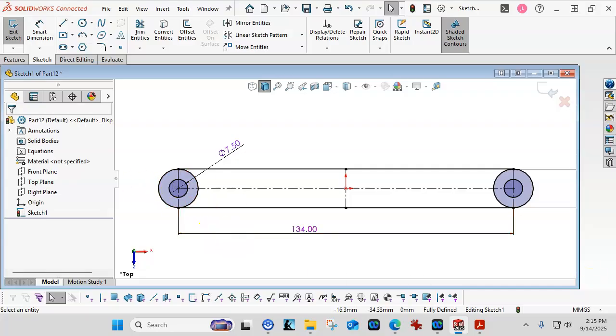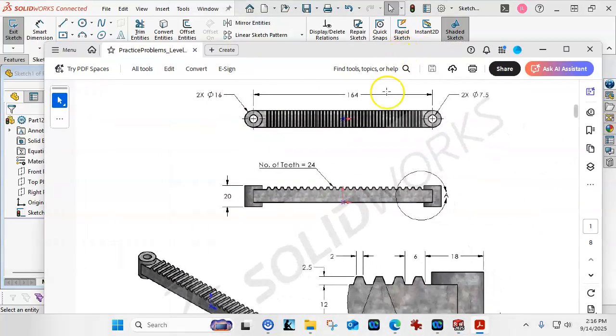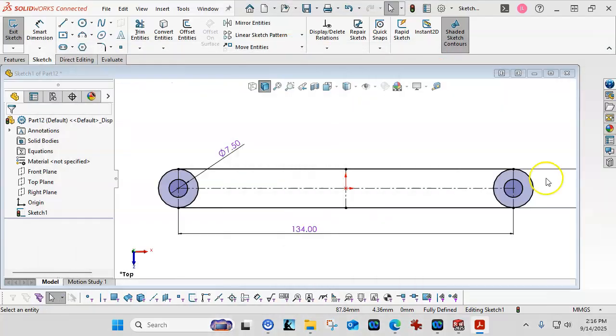Since we're going to have multiple features anyway, and we're going to do the math for this, let's go ahead and extrude the center section, because with the shared sketch, we're going to be able to get from here to here, but then I'm still going to have to add geometry either lower or above to get it to that offset, to that length.